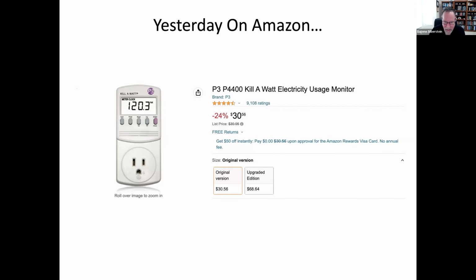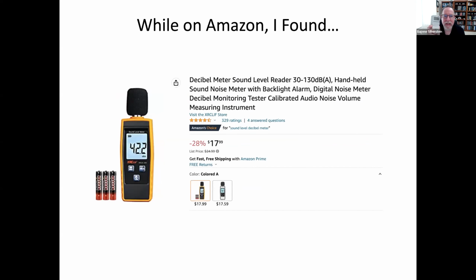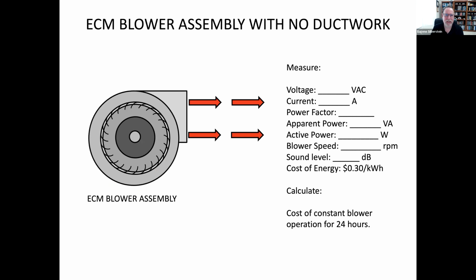And one other fun thing that I like to get is a decibel reader. It's a sound meter. Because as the air distribution system gets smaller and smaller, or is undersized, the amount of noise created by the blower increases. So what do we as HVAC techs do? What are we trying to teach our students? Well, we're trying to teach comfort. We're trying to teach how to heat, how to cool, but we're also trying to teach how to do it as effectively and efficiently as possible, and also do so at noise levels that are not excessively high. So I found those two on Amazon, which is actually pretty cool.